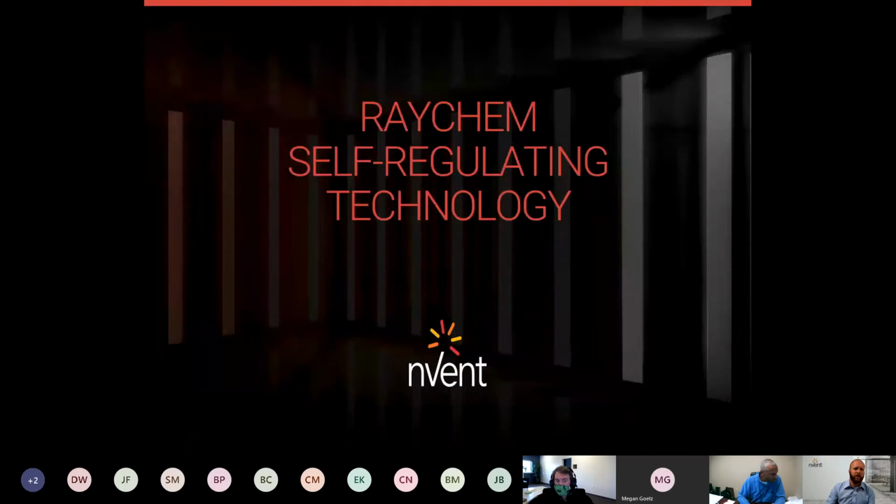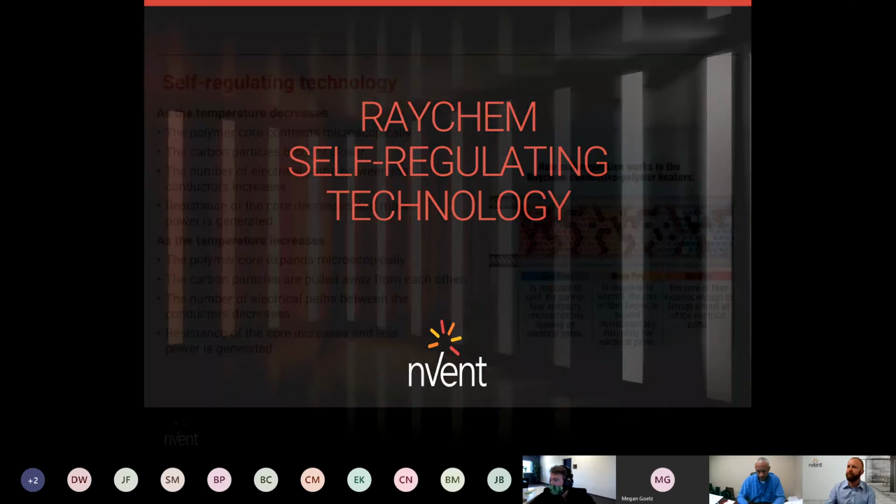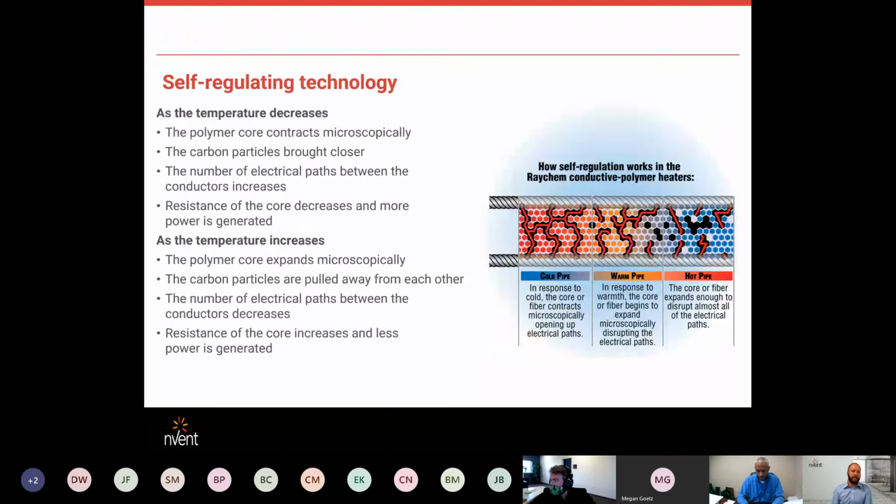Right now we'll talk a little bit about the self-regulating technology, which is again the largest portion of heat tracing in the world, done with self-regulating technologies of the electrical type. So what is self-regulating and what is not self-regulating? I'll get into that and a little bit about how it works in these next few slides.